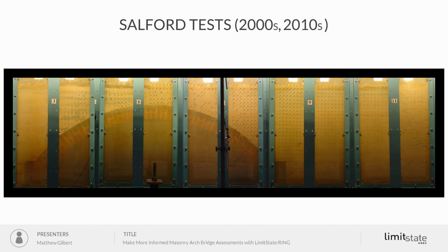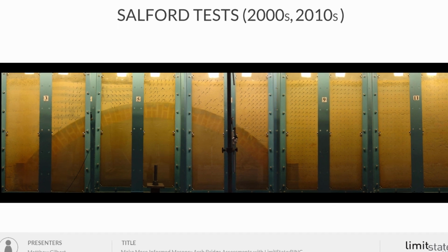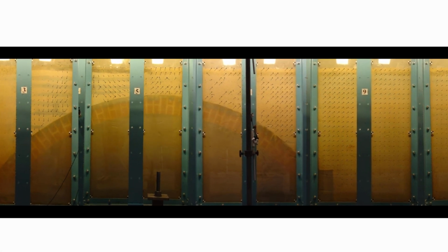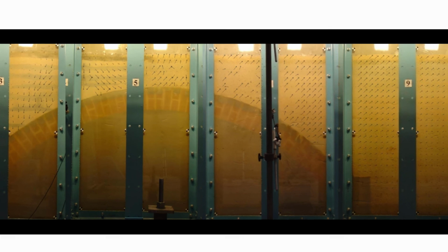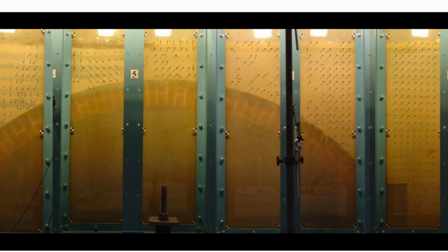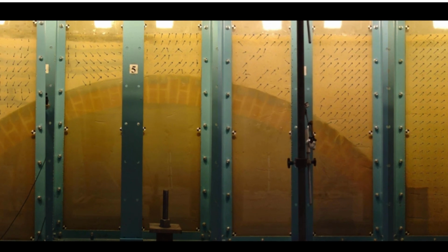And more recently, we've been looking at soil arch interaction in a bit more detail, and we've actually got here shown on screen a bridge that's been constructed in effectively a large fish tank. This is a 3-meter span arch in about an 8.5 meter long fish tank, and you can use digital imaging techniques to actually track how that fill moves around relative to the arch when an arch bridge is loaded.